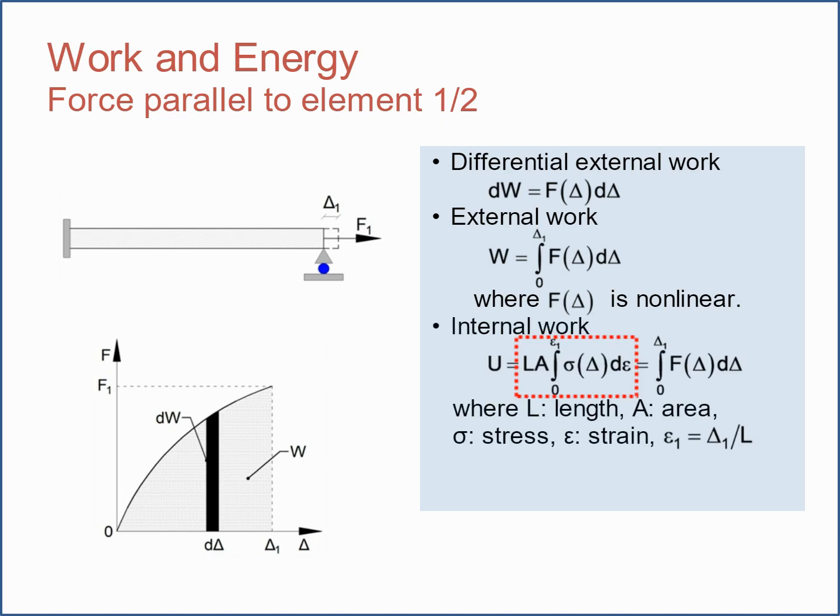The internal work, U, is equal to the volume of the element, which is given by the product of the length times area, times the integral of the stress, integrated with respect to the differential strain, d epsilon.